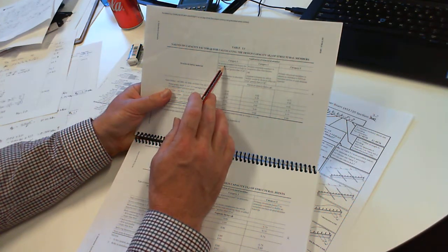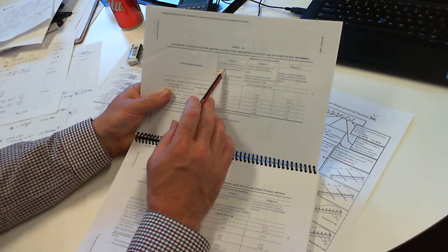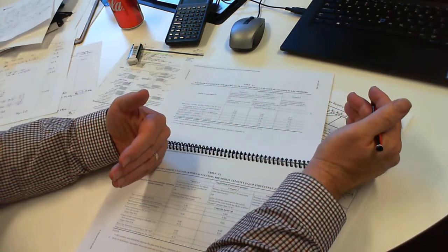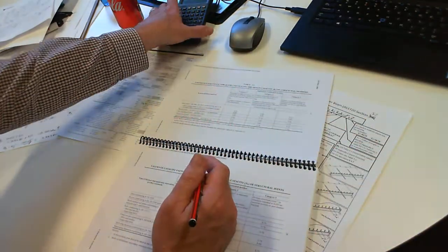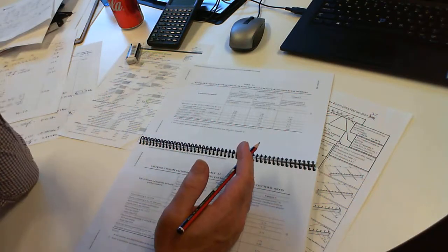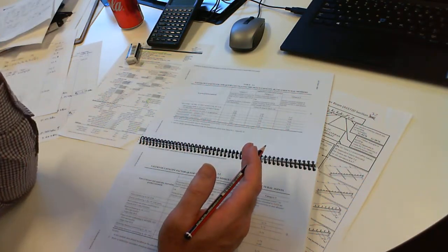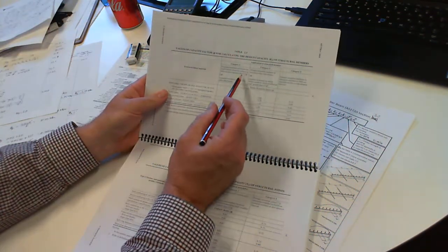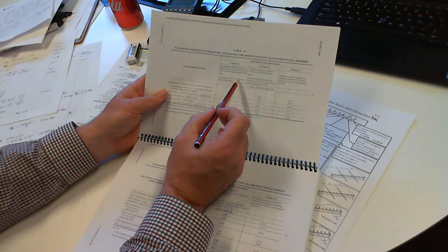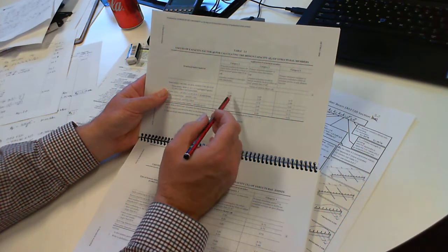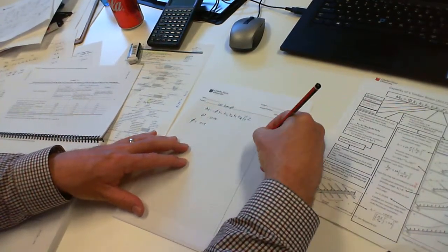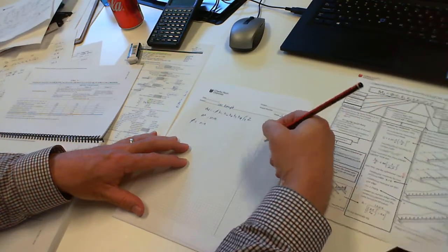So category 1, structural members of houses which failure will be unlikely to affect an area of greater than 25 square meters. Now we know that this beam was 6 meters long and it's every 900 mil. So if we go 0.9 times 6 meters, if one of these beams failed, it will bring down about 5.5 square meters of roof. So that's less than 25 square meters. It's also a secondary member in a house, so we're looking for a value of 0.9. Okay, so phi equals 0.9, and that comes from table 2.1.